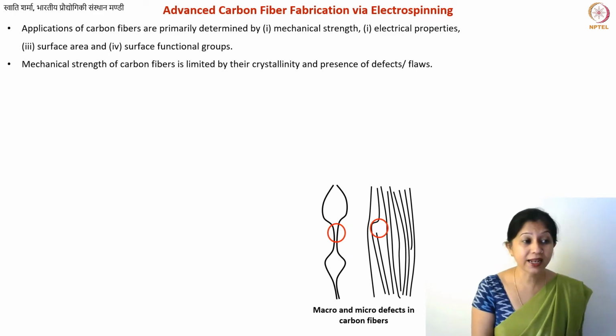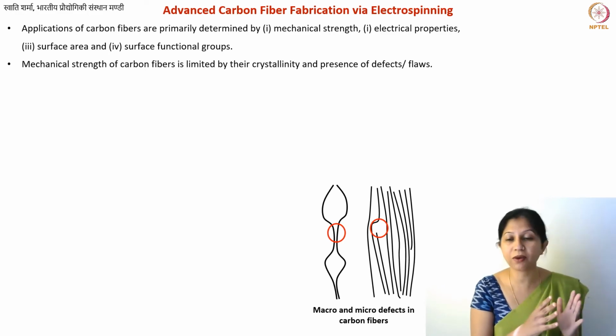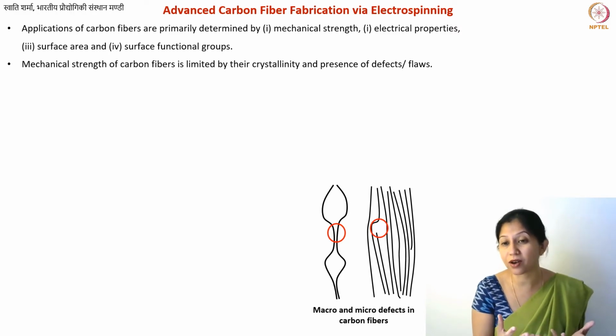But when there is any tension or fatigue or any kind of mechanical deformation, these cracks or these voids are where you're going to have your cracks and breakage. So these are the possible defects in the case of carbon fibers. Some of them we can avoid, and some of them we cannot avoid.